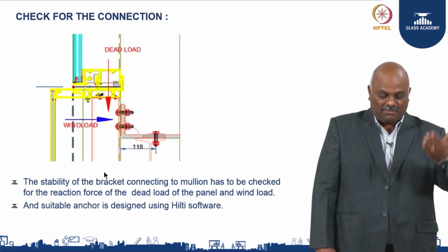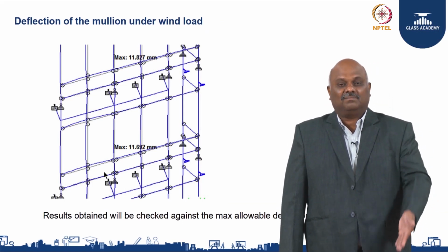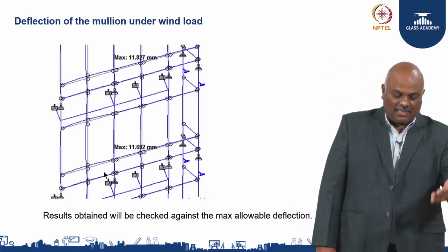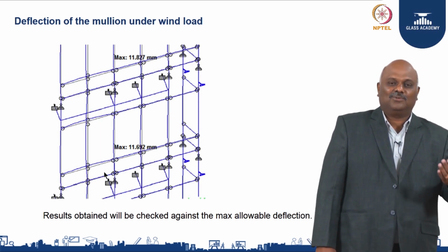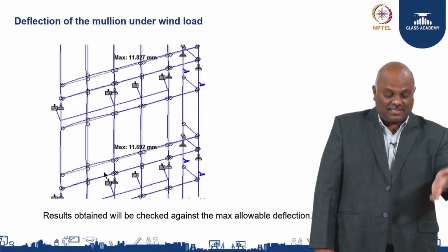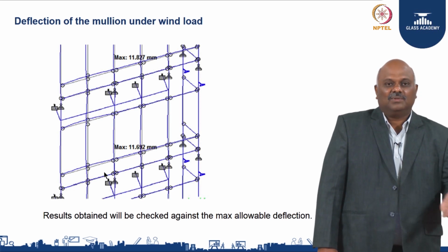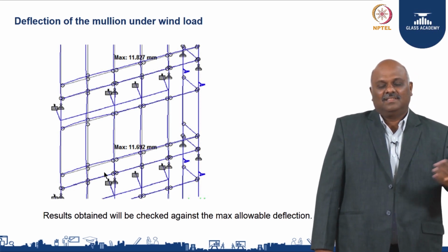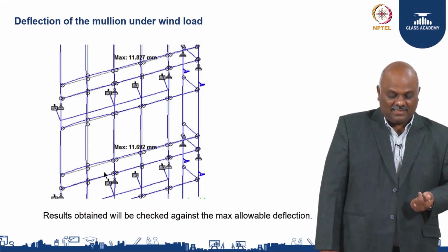So it is like calculating a simply supported beam or a column, right. So run through the program, or even manually you can do it, but people nowadays do not do too much manual calculation, they always go with the software available. This gives you complete detail. So you start in reverse, the substrate first, then the design of the mullion, followed by the transom and other things.